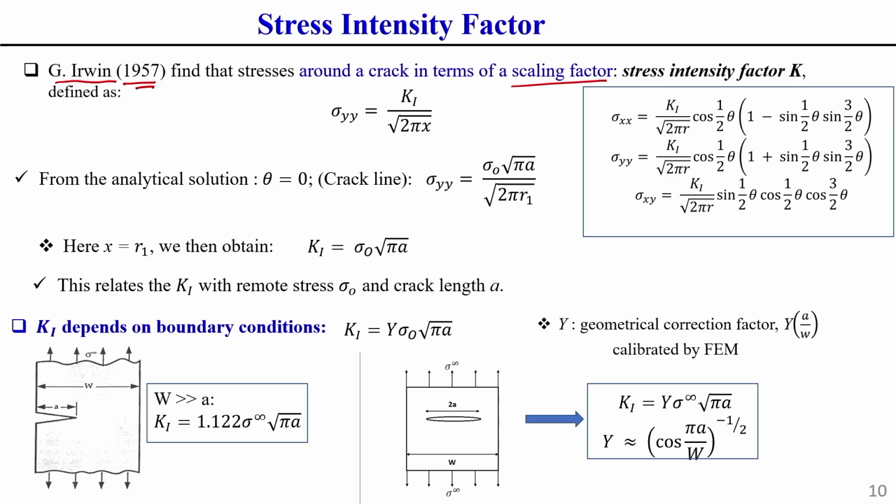This scaling factor is called the stress intensity factor. How do we find this stress intensity factor? That is generally represented as K1, as I am showing. So, for the analytical solution which we have got, I have already shown sigma xx, sigma yy and tau xy in terms of this K1.